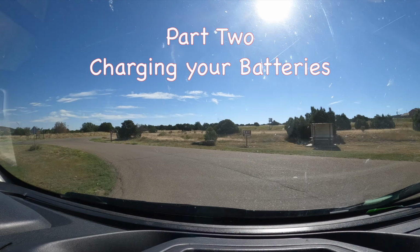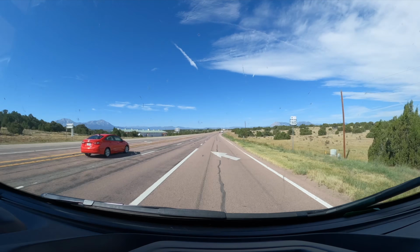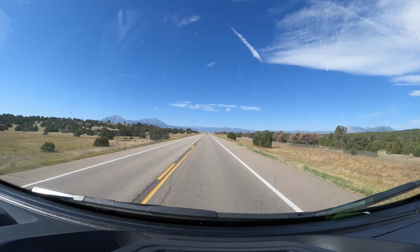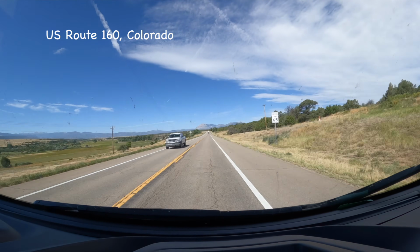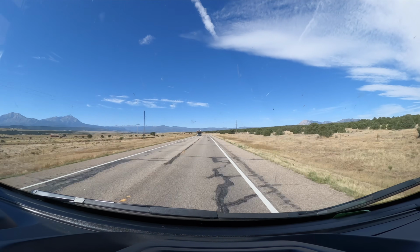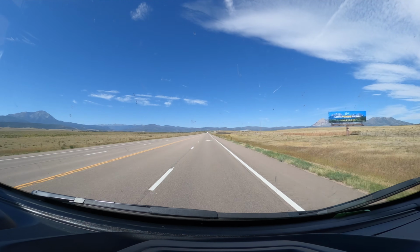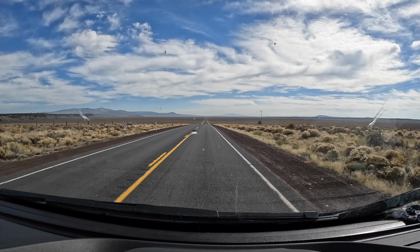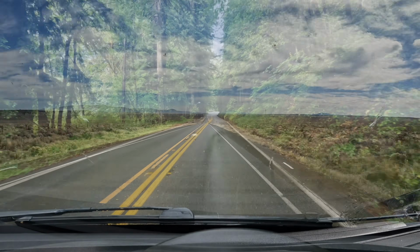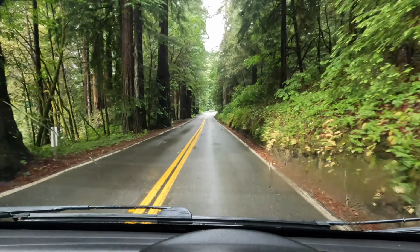Here are a few things you should consider when deciding how to charge your battery bank. How quickly you need to replenish the power you consumed, whether or not you'll be driving each day, the amount of available sunshine, and if you will have access to shore power. Part of this consideration will be your own personal preferences and lifestyle. We usually drive each day while traveling, and if we are parked for the day, it's often sunny. We rarely have access to shore power, so that side of the charging equation is negligible.